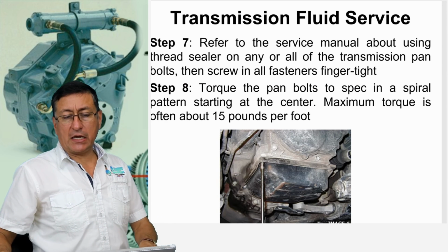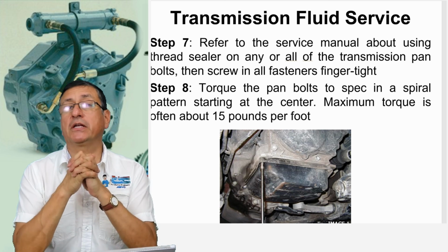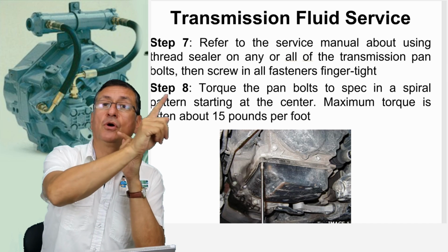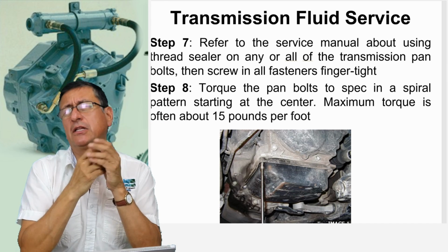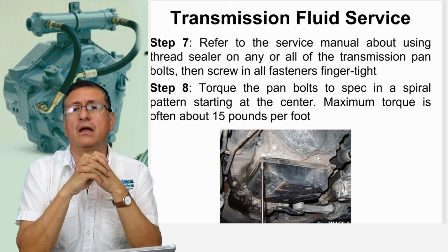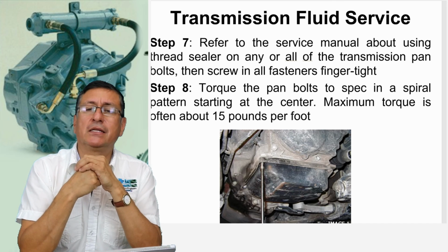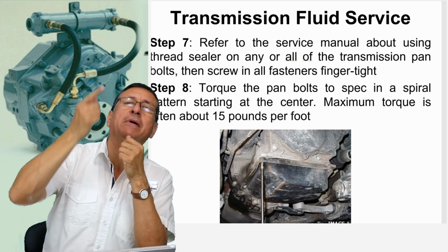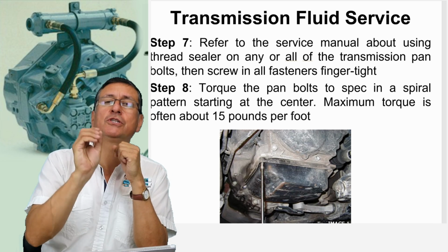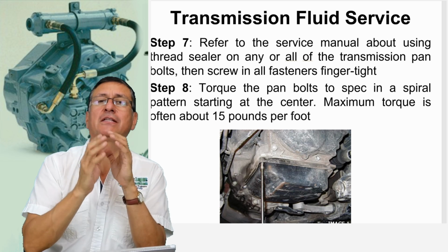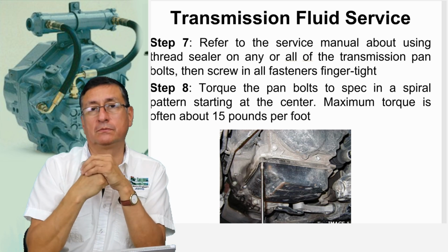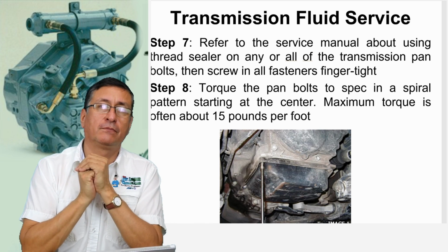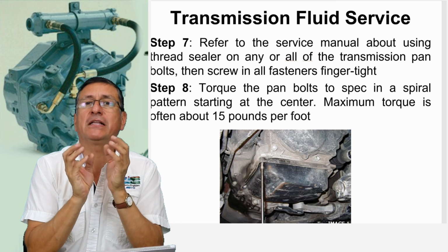Okay, my friends, and right now with respect to the service manual, check the procedure to tighten those bolts, and the torque recommended is normally around 15 foot-pounds, but it depends on the manufacturer. Don't try to tighten more because immediately you damage the thread. The thread of those bolts is too sensitive. It's easy to damage that. Don't use an impact tool because you damage the thread of the bolts. Believe me, with your hand, with the ratchet. This is a sensitive material.